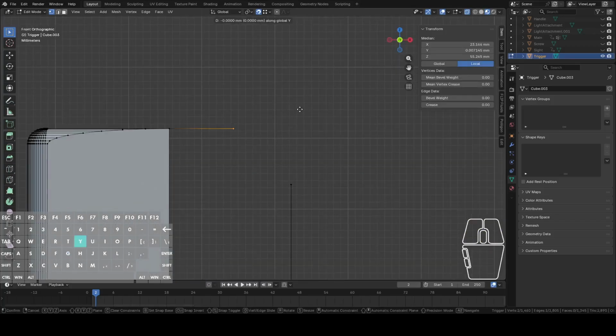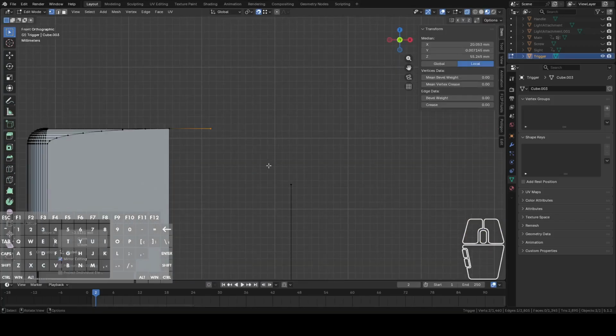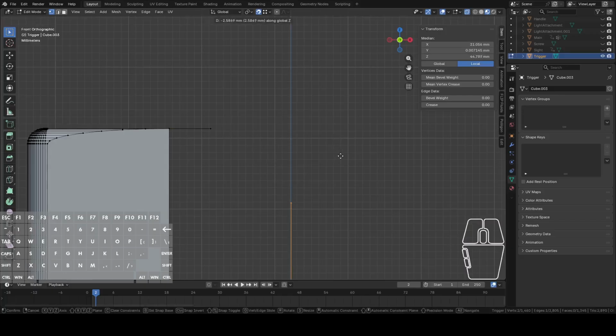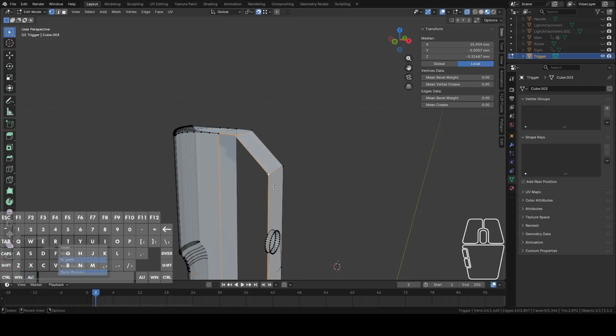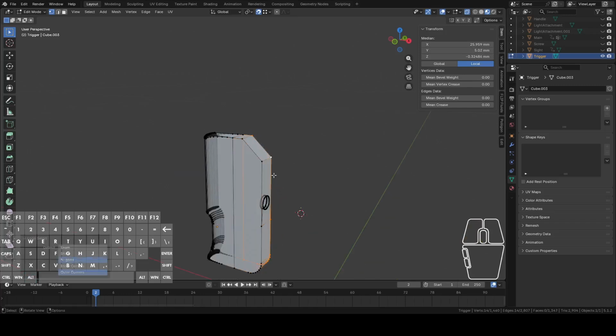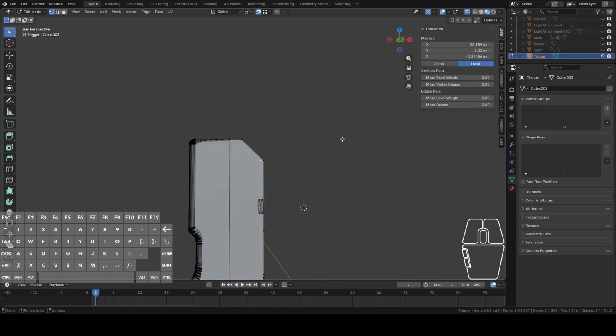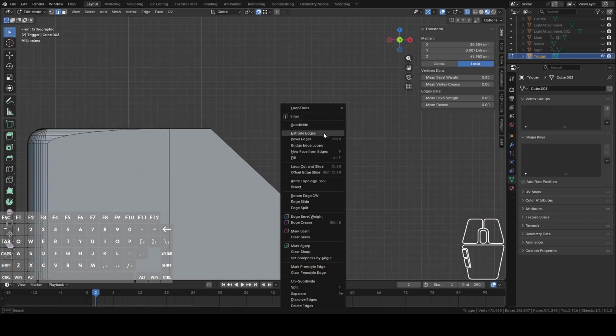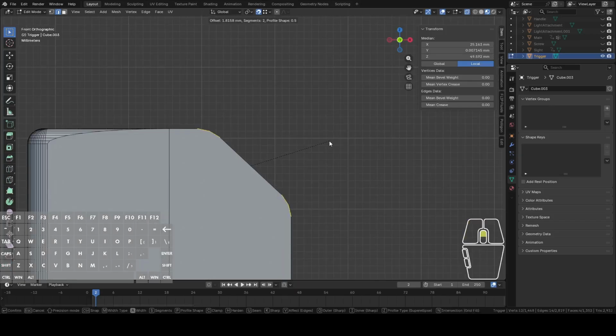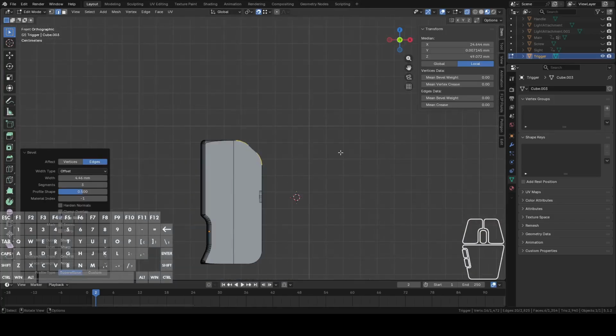And then we're going to push this over a little bit with GX, GZ over here to open this up. And then we're going to put a face there. Gonna seal that up with F on both sides. And then we can bevel these a bit. I don't know if this is going to work. I'm just kind of hoping. Based on what I've seen so far, it could use the room.